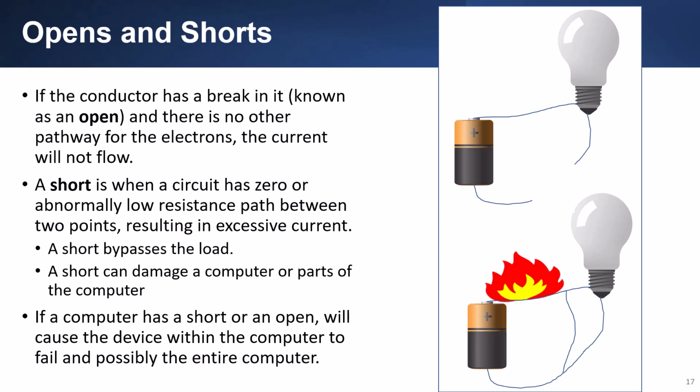If a computer has a short or an open, the device that has a short or open will fail and possibly cause the entire computer to fail. Usually, you will not be able to see a short or open as readily as in these two pictures. All that you know is that the device does not come on, it starts smoking, or it catches on fire. In fact, the computer power supply tries to detect shorts and opens. It will shut down to protect the computer and the user.